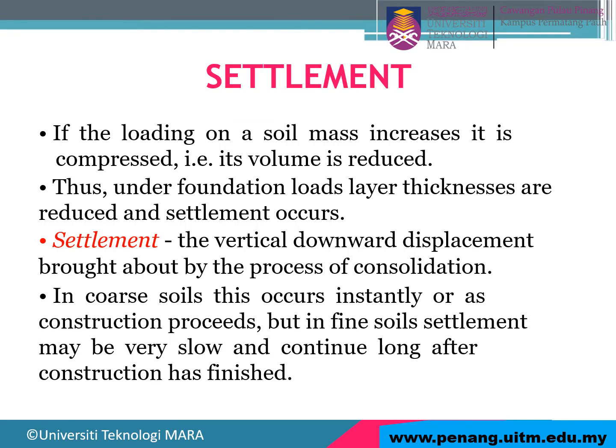Now we go to settlement, because settlement is actually related to consolidation. So you imagine like this. When we apply load on the soil mass, of course, the load will compress the soil, and the effect is that the volume of the soil will be reduced. Similarly, under foundation load, the thickness is reduced and settlement will occur.